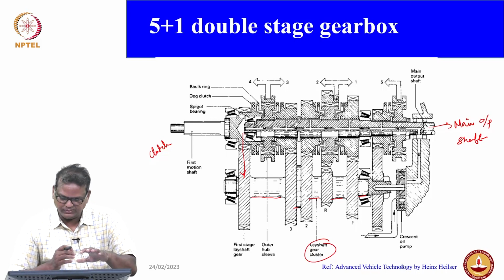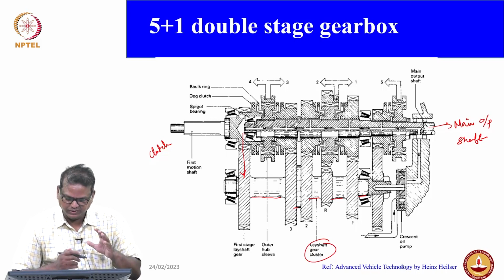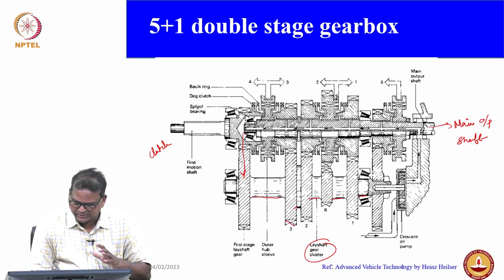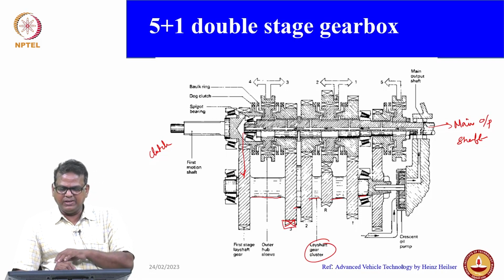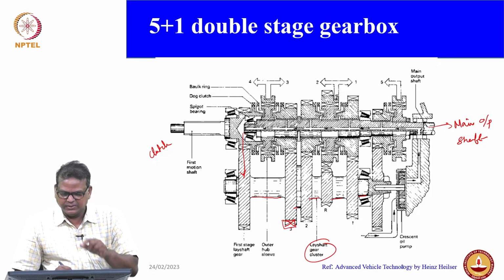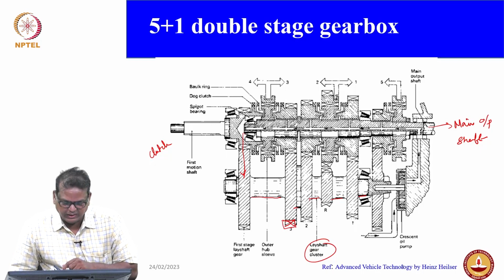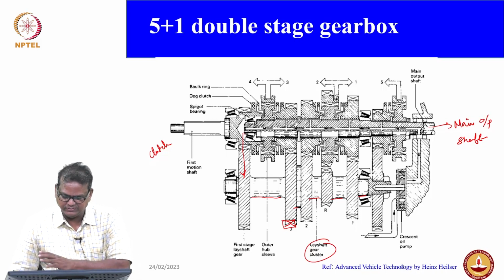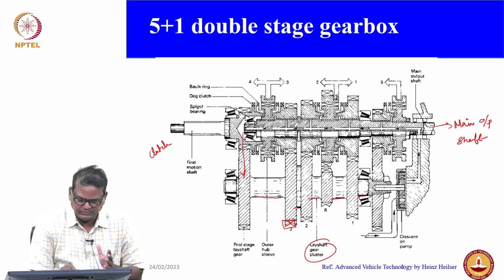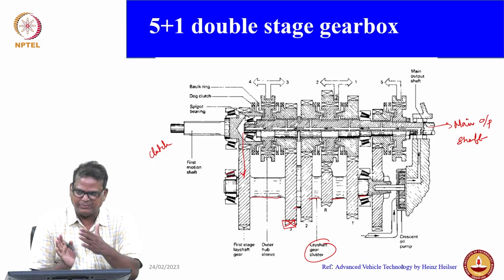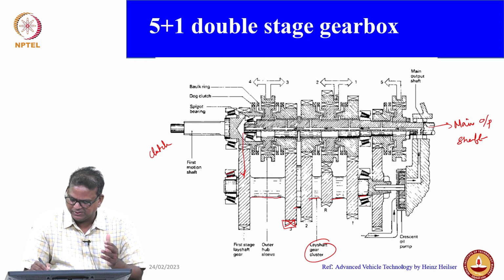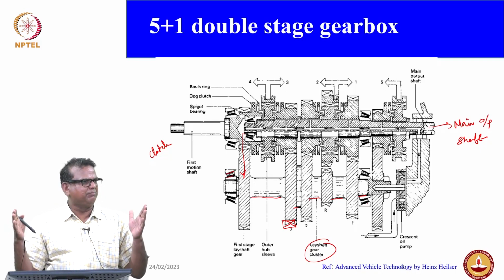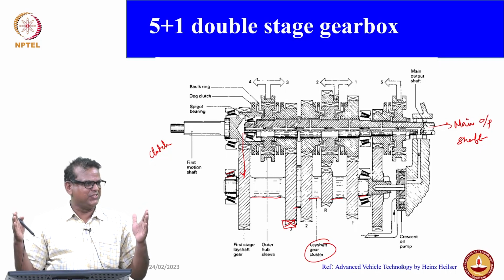Okay. And actually this is the synchromesh arrangement. Look at that. Anything indicated with this symbol is for the bearing aspect. These are the bearings which are supporting the gear; you can see that arrangement. And interestingly, if you look at the lay shaft, this is the bearing, and there is a nice taper roller bearing at the end, right. Here also you can see the nice taper roller bearing. So that means it is a kind of simply supported beam arrangement.